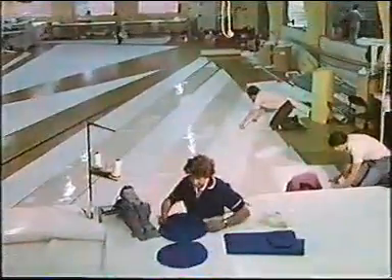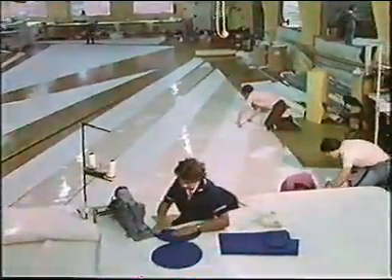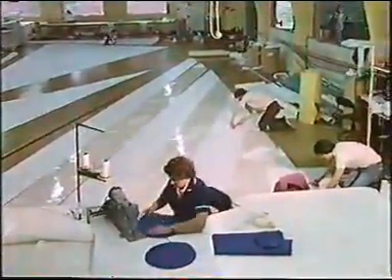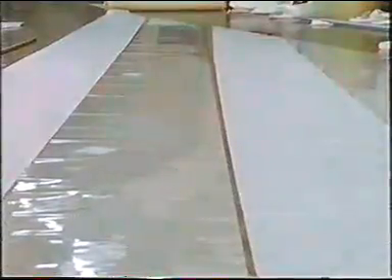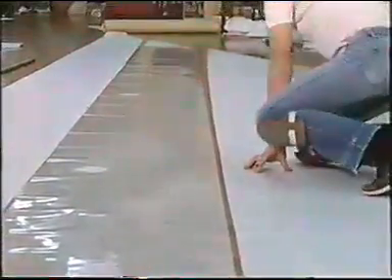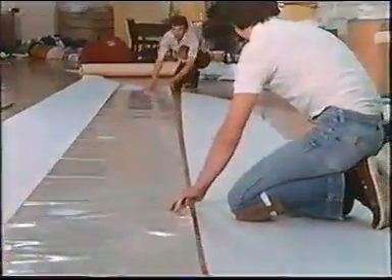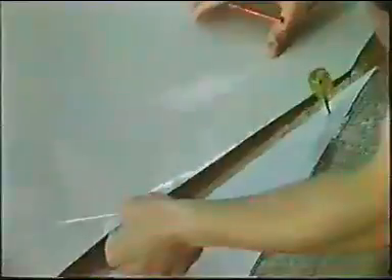This is a sail loft at Bruce Banks Sails, one of the largest in the country. It's here that the cut pieces of cloth are laid out before being sewn. You can see the subtle curves on these two pieces, which are about to be joined together to an accuracy of the thickness of a pencil line. And that means very precise calculations.